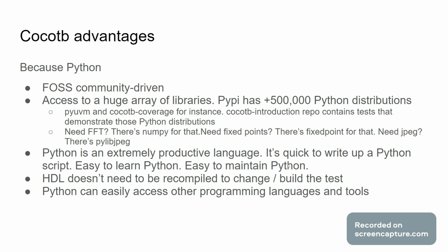And a nice touch is that Python is an interpreted language. You don't need to recompile all of your HDL when running your tests. You can just start your test over and nothing needs to get recompiled. And again, there's a high focus on just getting the test done. That's really the big advantage here when writing in Python. Just getting the test completed and running is the big advantage. You spend less time on development that way, and get closer to having something that works and does what it needs to do.